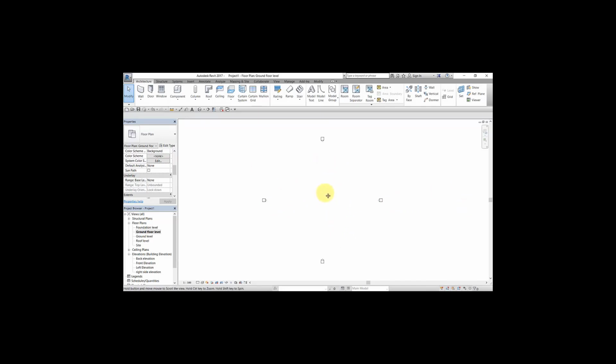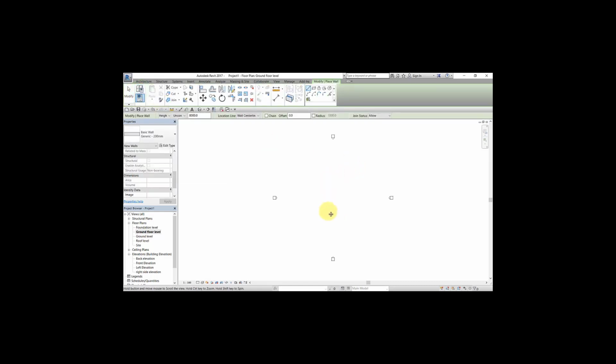So now let's go straight and pick our walls. From our previous lessons, what we learned was that if you want to pick up anything that concerns modeling of the structure, the only place that you can get it done is to come to the architectural tab. In clicking the architecture at the tab bar, we'll find our wall there. So we click wall, and that is it. You can go straight away and draw your wall. But there are some few things we need to take note of.